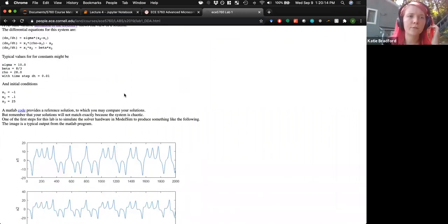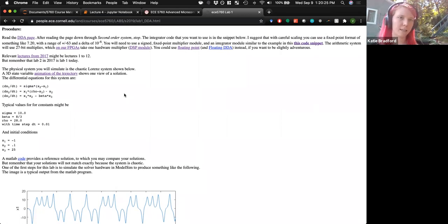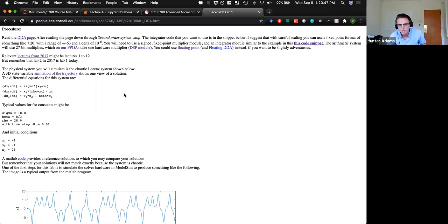So just to clarify, the inputs from the HPS to the FPGA for the final implementation will be the initial conditions and DT. Should the FPGA be keeping track of the current state? So you'll pass in the initial conditions and the parameter values for sigma, rho, and beta. I don't believe it's required that you pass in DT. Okay, so that can be hard-coded. Bruce, can you concur? Or is that a parameter that you want passed in?